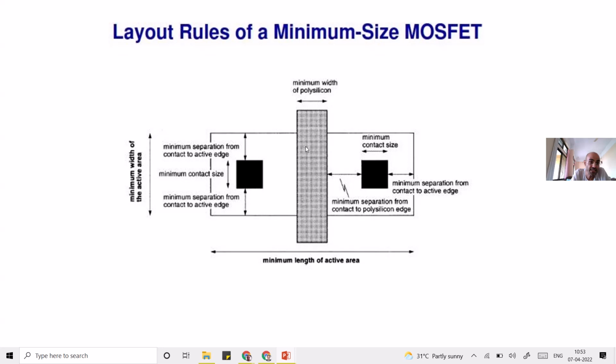So let's say you're just making a single device, and it is asked what the dimension of the device is. Then you have to calculate, in a particular technology in which the minimum feature size is already given, what the minimum polysilicon layer is which you can grow. This will become your gate length. Whatever this dimension is given in the problem will become your gate length. Then there is the distance between the source and the drain, where you will have these devices. Accordingly you can find it.